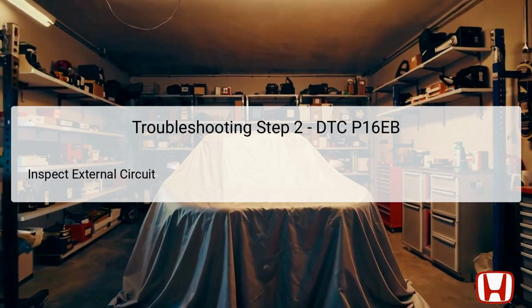The next phase is to inspect the external circuit, particularly focusing on the wiring and connections of the active exhaust valve, ground, GND, and the LIN battery sensor circuit. Start by ensuring that there are no visible signs of damage or corrosion on the wires connected to the active exhaust valve actuator. Use a multimeter to measure voltage continuity in the relevant circuits, specifically checking the LIN communication ability